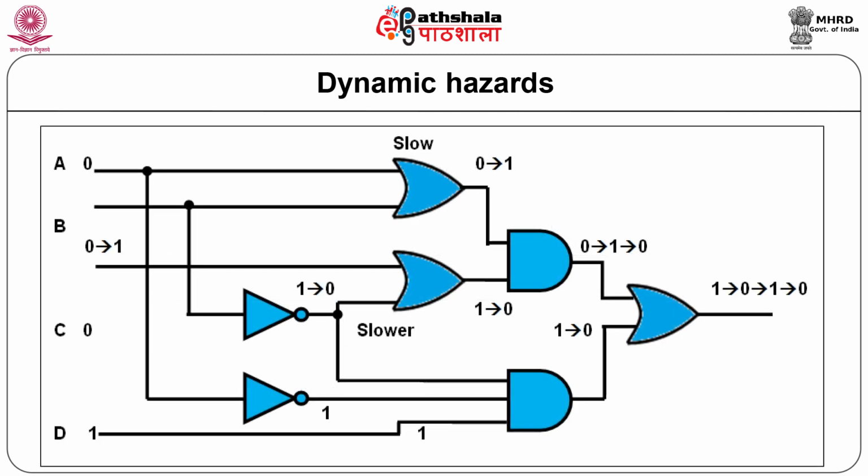When multiple glitches occur at the output from multi-level circuit because of changing inputs, the only reason for this could be existence of 3 or more asymmetric paths, that is delay wise, of that input to the output. In such a circuit, routes may have different delays.